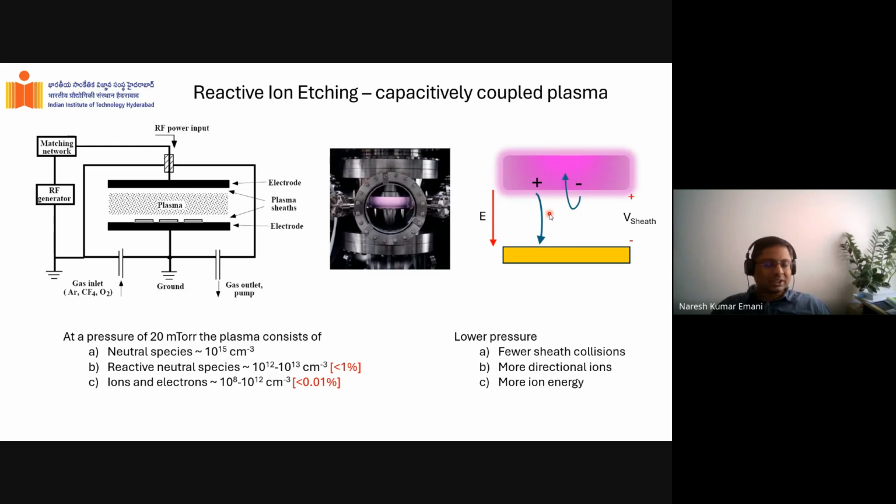So you are creating a stronger plasma, but automatically the velocity with which they're striking the surface is also changing, and it's increasing, right? You're creating a stronger plasma, but then you have a larger number of positive ions here, and then they will strike with a greater velocity. So you might actually damage. What happens if your velocity increases?